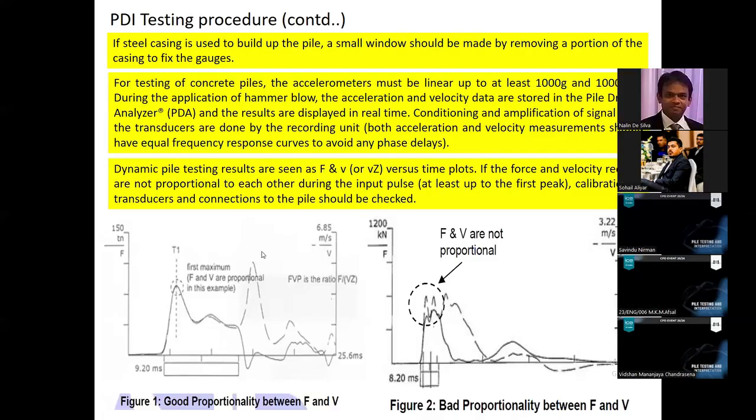I told you that we are using a number of sets. So this is the average response. Average force response taken from the strain gauges. The solid line represents the average force response. The dash line represents the average velocity response. So velocity is actually obtained using the accelerometer.